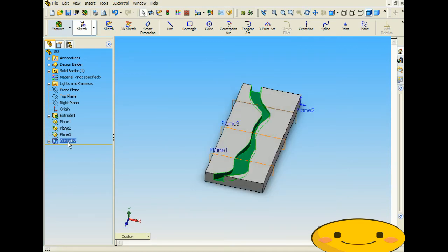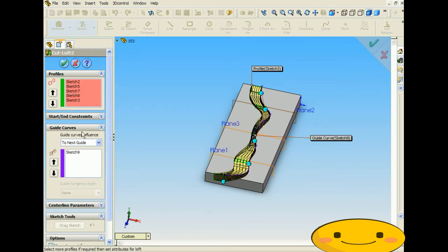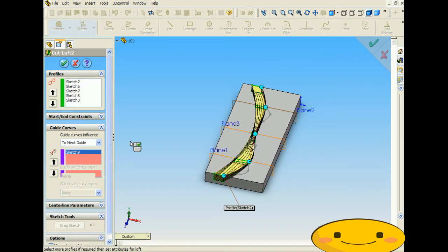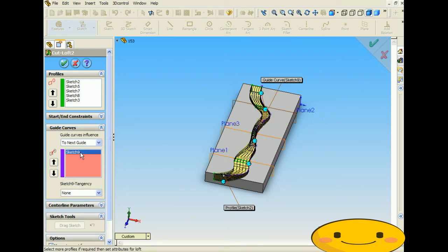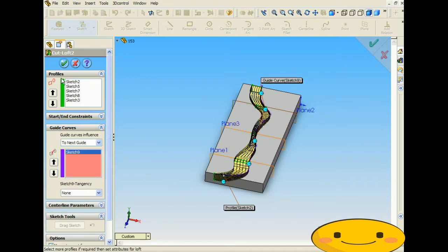Now if we go back into it to edit it, if you notice when I was playing around with it there, I only had the first 2 showing. You might have to go and take out the profile and then put it back in sometimes just to get the right curve, just because sometimes the feature, like this function here, is going to select things in the wrong order and it might screw up what it's going to look like at the end. So something like the path you might have to delete and then put back in. Alright.